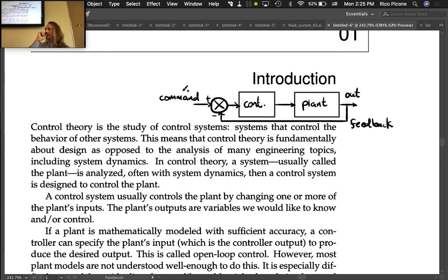Actually, a purely mechanical control system that's pretty fun is the toilet. The float valve on a toilet is essentially measuring the height of the water in the tank. When it gets to a certain height, it closes the valve supplying water to the tank. And then when you flush it, the level gets lower, it opens up the valve, and it starts refilling. So it's an example of one of the earliest control systems that we know of that were designed: a float valve shut off.